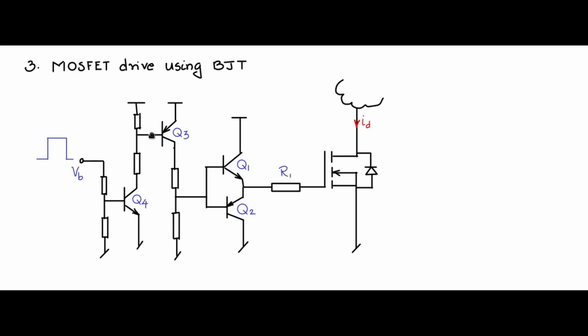It could become hundreds of milliamp sourcing capability at this point. It can increase by another factor of HFE SAT here. So you can get in terms of amps, another factor by HFE SAT, you can get in terms of tens of amps. So you can get really very high sourcing capability at this point when you are having multi-stage BJTs to amplify whatever the current here to a large value of Ig plus.